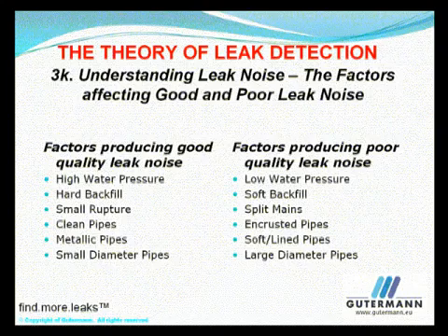Clean pipes create a louder leak noise than encrusted pipes. Metallic pipes create a louder leak noise at a higher frequency than soft or lined pipes. Small diameter pipes make a louder leak noise at a higher frequency than larger diameter pipes.